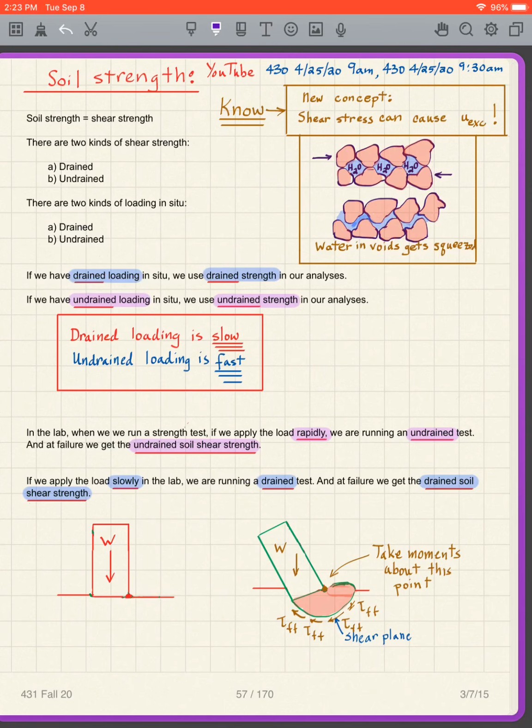when the particles move, the particles fall into or move into the voids, and when they move into the voids, they compress the water. So the water originally starts out with a lot of void space. It goes down to little void space. Well, what happens? The particle going into the void presses the water, and the water gets squeezed, and it creates excess pore pressure.